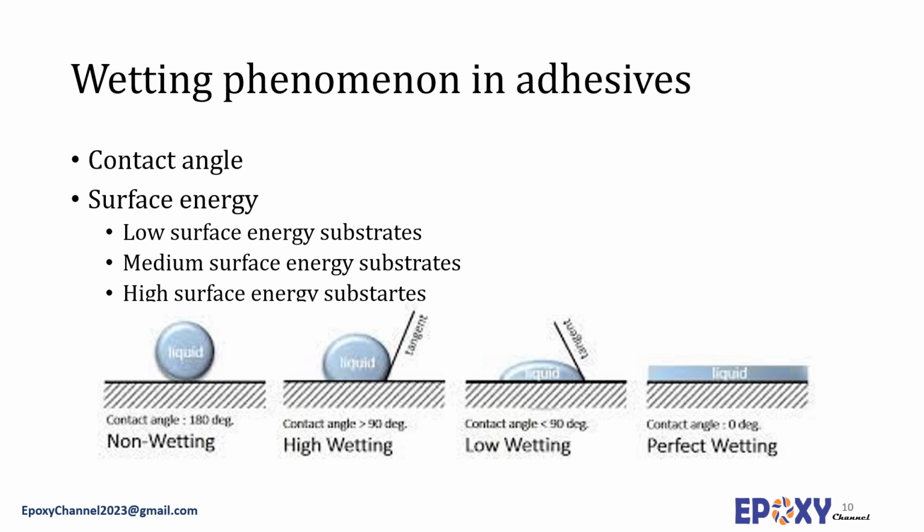Based on surface free energies, solid substrate surfaces can be categorized into low surface free energy solids, for example fluorinated and hydrocarbon polymers with a surface energy around 20 millijoule per square meter, polymers with considerable polar characteristics, and high surface free energy solids, for example, inorganic materials and metals with free energies of often more than 500 millijoule per square meter. Epoxy adhesive exhibits a surface energy of approximately 45 millijoule per square meter.